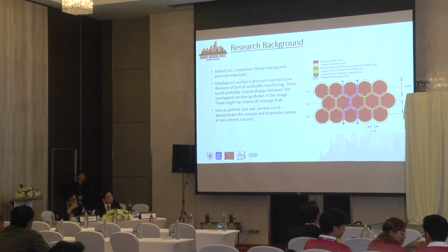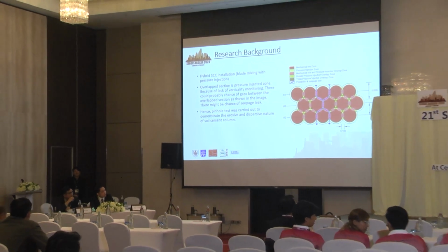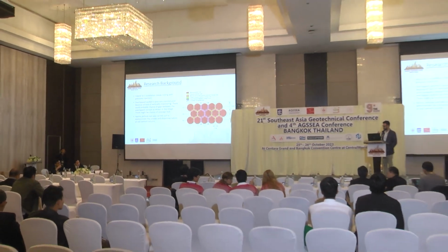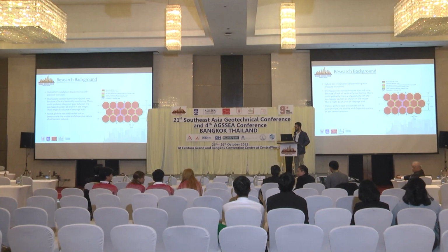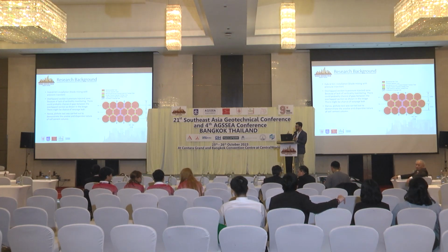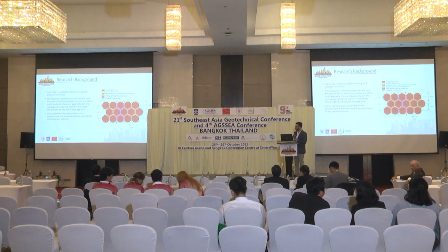In the field, we found that dispersive soil was present. When the rehabilitation work was carried out, we found the dispersive soil in the dam section, and half of the work of the soil cement column was already completed. So we wanted to make sure that the cementation process would change the dispersive property in a positive way, sir. That's why the laboratory test was carried out, sir.